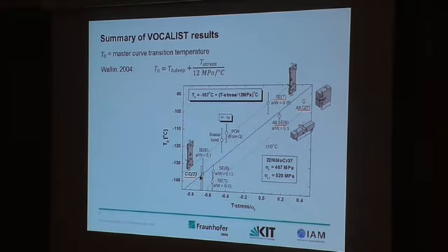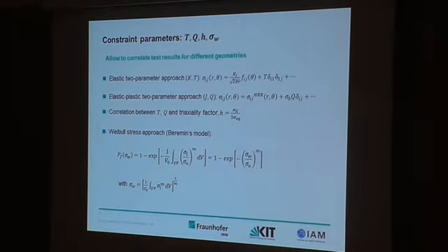Of course, it's a convenient approach, but the engineers need something maybe more simple, and which is easily applied to assessing components. And such two methods exist. Before I start with the methods, I will also briefly tell that beside the T-stress, there are other constraint parameters which can be used to calibrate the specimens or to correlate fracture toughness data on different geometries.